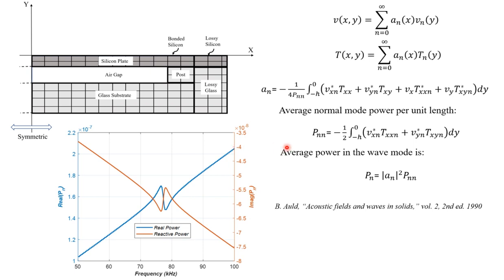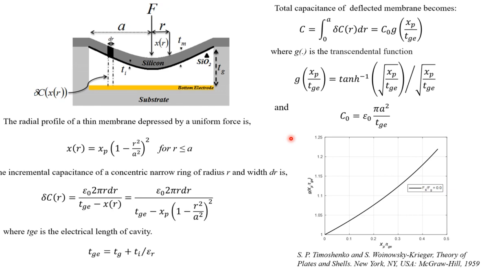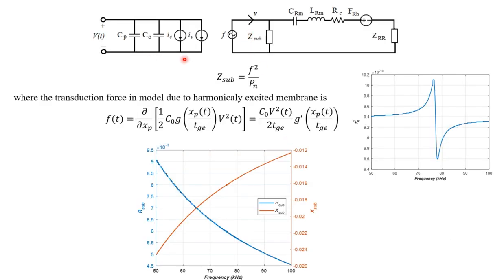let me show you a circuit right away. So I think I have a circuit over here somewhere. Yes. So you can see in typical transducer equivalent circuits, you have an electrical section and a mechanical section. So the substrate loss is across the transduction force. So what it means is that if you have the power from FEM, which you have calculated in terms of the tensile stresses and the velocity of the waves, so this transduction force is what is responsible for making sure that propagation happens into the backing.